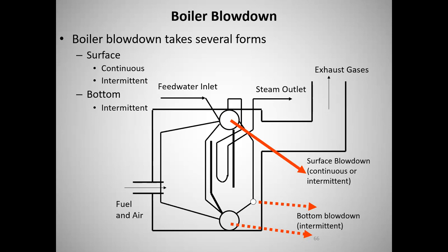Now, if you have a use where you don't mind having high mineral content someplace else in the plant, but you don't want to put that water back into the boiler unless you clean it up first. But yes, you can, and that's where we're headed in the next couple of slides, blowdown heat recovery systems. Some plants have them and they don't work right, and a lot of plants don't have them at all. It just depends on what they purchased when the plant was put in. But absolutely. Okay, that's the surface blow.